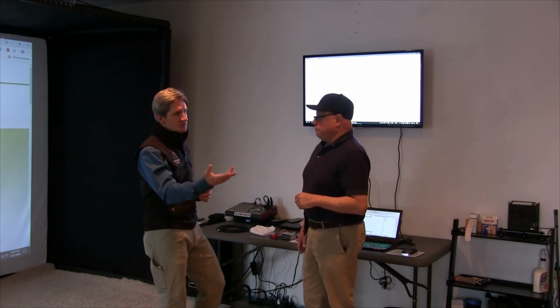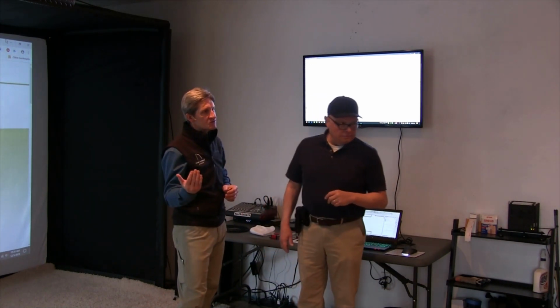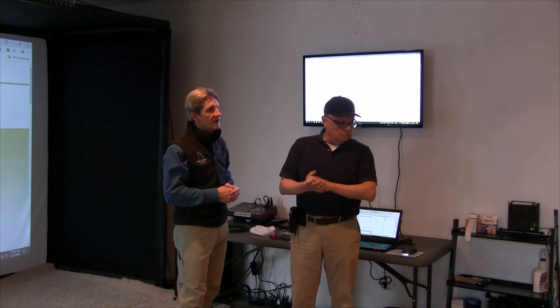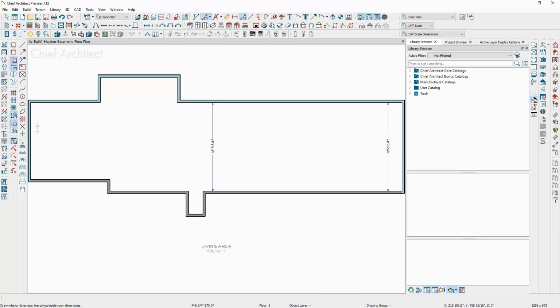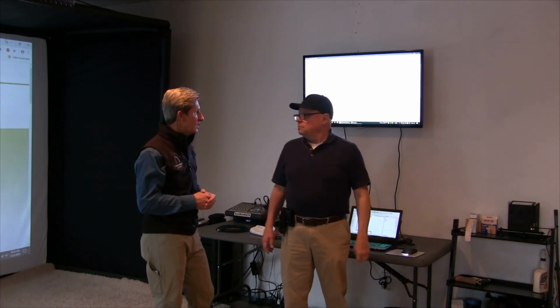So this room's maybe 70 feet long. How many dimensions will you take across that room to make sure that you have a square condition, do you think? From this room, there'd be 3 from the far wall here to the stairs, probably 2 on the intermediate indentation, and then 2 on the far area, just to make sure. And really the purpose is just to make sure you've got a square.